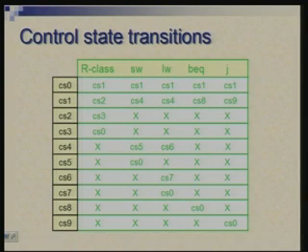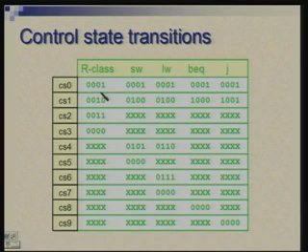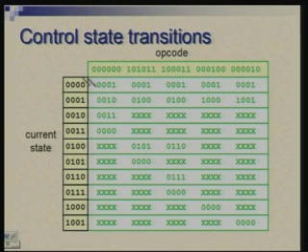This table can also be replaced by a binary equivalent, where we substitute a code for each of the control states, and also we specify the opcode value for various instructions. So after having replaced the control state codes in this table, we get this. On this column also we replace all the states by their codes, and opcodes are also put there.